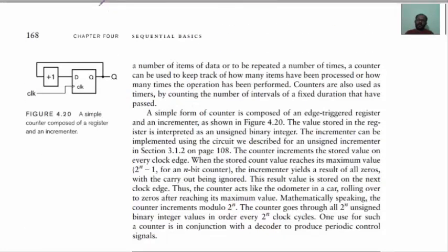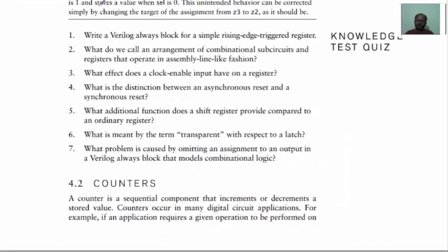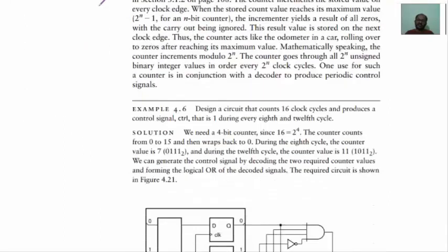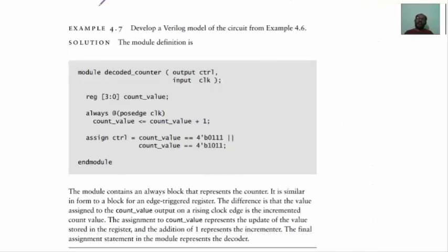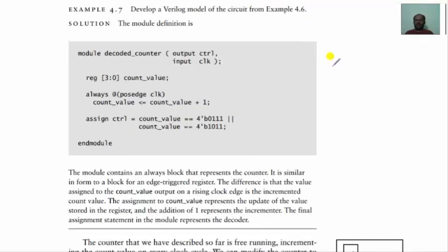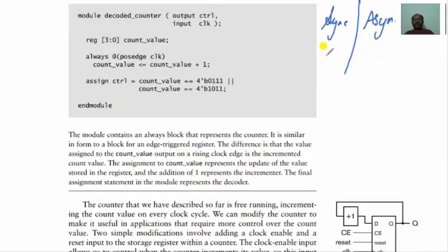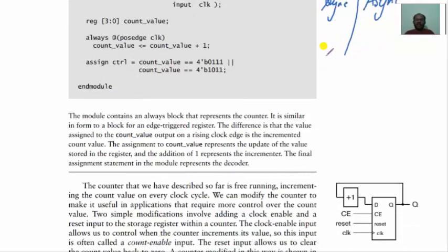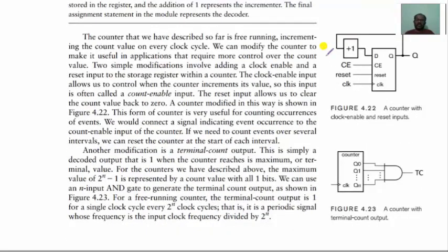Let us talk about counters. Counters are sequential circuits which perform either increment operation or decrement operation based on how you apply the clock pulse. If I am giving clock pulse to each and every flip-flop simultaneously, it is referred to as synchronous counter. If you are giving clock to the first flip-flop, and for the second flip-flop you are deriving it from the previous output, then that design is called asynchronous design. You can realize the up counter and down counter using two techniques. The first one is synchronous technique and the second one is asynchronous.